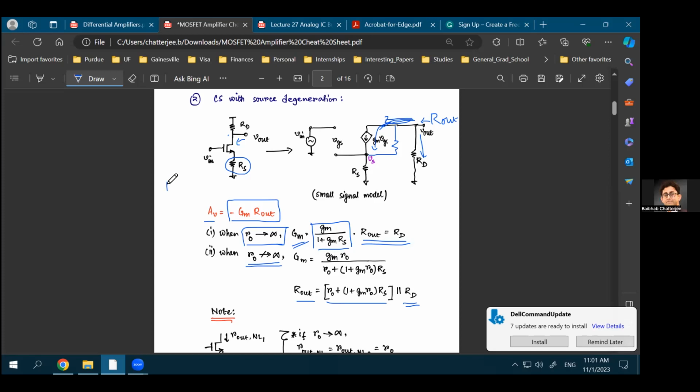in simpler terms, and this is something you can remember, the intrinsic gain of the transistor is Gm times RO, right? So the resistance connected at the source will be multiplied with this Gm times RO, and then you can add an additional term RO to that, because RO is the resistance between drain and source of this transistor. So RO is the resistance looking between the drain and source of the transistor. But in series with that, you have an RS term. But that RS term sees an amplification looking into the drain of the transistor. And we have solved this two lectures before.